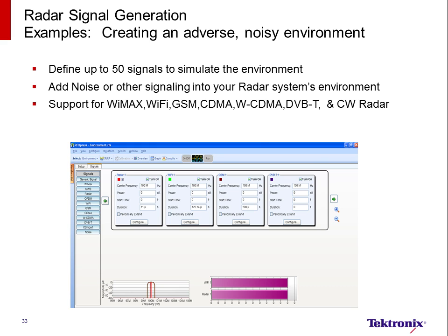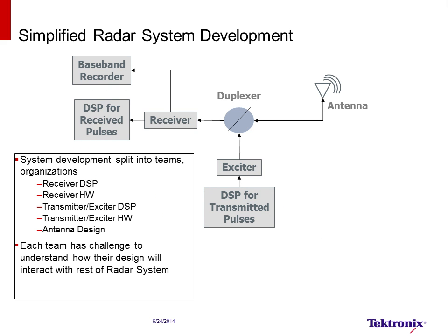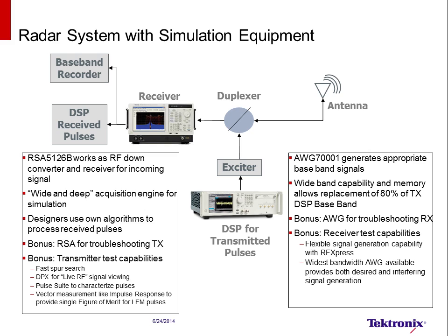So here we're looking at a simplified radar system in development. All of the different pieces are in development at the same time, typically. Although the team could wait until final integration to verify that everything plays together nicely, testing earlier in the process is obviously less risky. By substituting flexible test equipment for sections of the radar design, many of the other radar sections can be tested with reasonable certainty of interoperability with those sections that are not yet designed. This is also called de-embedding.